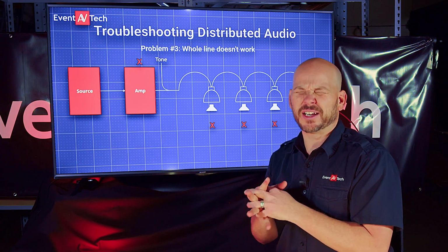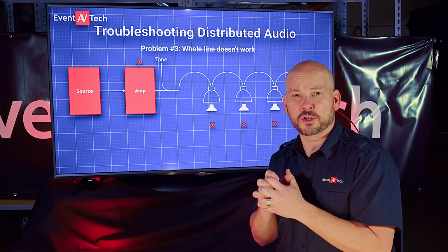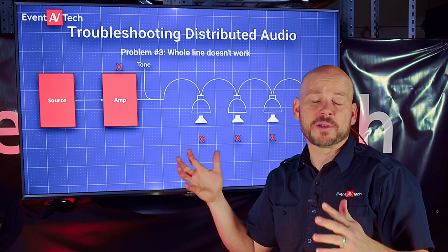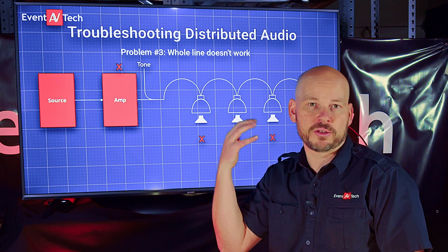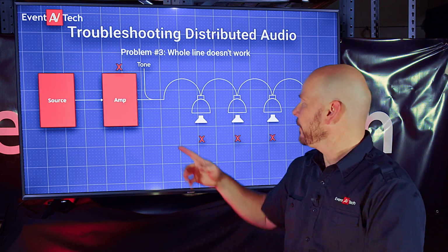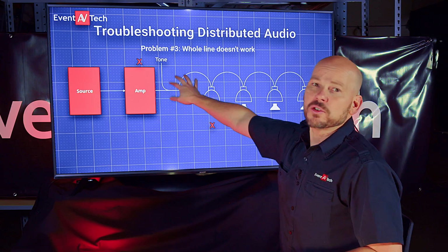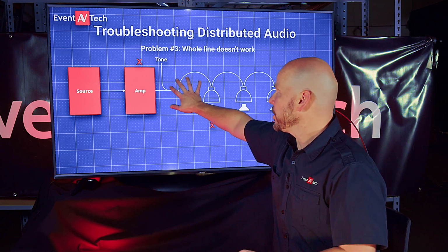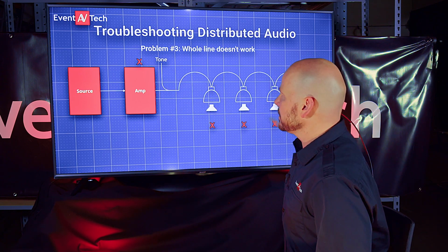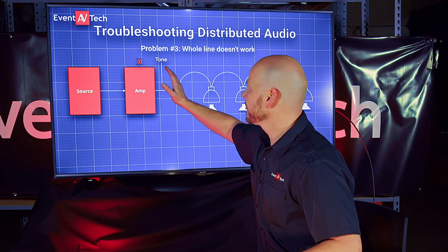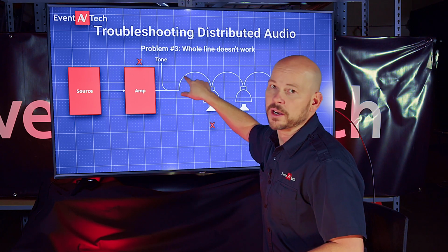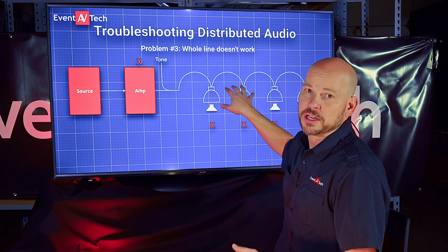You gotta remember that it's only a 9-volt battery. It's not super strong, so it's not gonna be really loud, but it should be loud enough for you to put your ear up near the speaker and hear if the signal is passing. We use this technique a lot because we want to know, do we have good speakers and a problem elsewhere, or if that doesn't work, then we definitely have a problem at our speaker location.